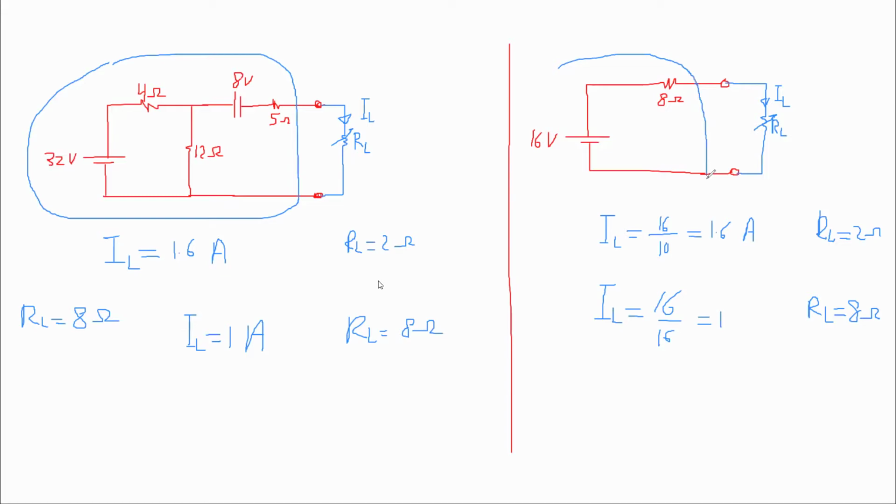Now someone would ask, why is the voltage reading here equal to this voltage? Here's an example. The voltage here is 12 volt. What is the voltage between these two points, here and here? It's going to be 12 volt. Why is that? Because it's an open circuit, no current. Current is 0. If there is no current, the voltage across here is going to be 0 volt. So basically, if it's 12 volt here, it's going to be 12 volt here. You're not losing or gaining anything.